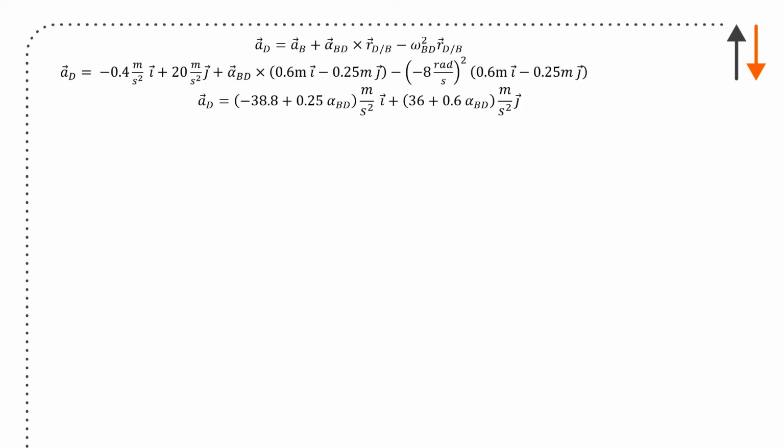So we then take our relative acceleration terms. Acceleration D equals acceleration B plus acceleration of D with respect to B. Substitute in the terms, and recognize that we have all of these expressions here. So when you're looking at this from that perspective, you have the tangential acceleration and the normal. And remember that, again, I didn't stress it too much on the last slide, this is only true when you have planar motion in the xy plane. You have to do it a little bit differently in each expression.